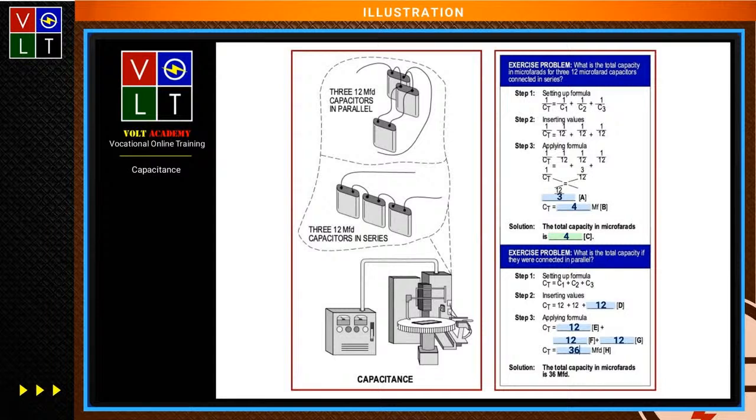Now, when I'm looking at a capacitor connected in series with the alternating current circuit, that current is allowed to flow back and forth in the circuit without actually passing through what? The capacitor. Right. I also will point out here that the electrons are going to build up on one plate of the capacitor and flow out through the other plate. And an electrostatic field is established that causes the current to flow in the opposite direction. However, as the voltage from the source begins to drop, the electrons start to flow away from one plate of the capacitor onto where? The other plate.